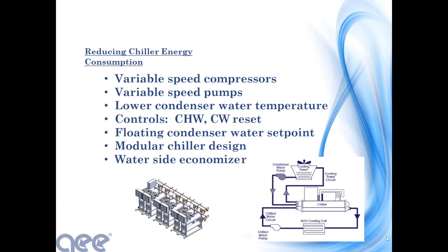So we recognize that with most of these electrical mechanical chillers, you're optimized at 50% load. So if you have, say, 2 chillers in a building, and your strategy right now is to run one as the lead chiller, and when it gets up to 100% load and you still have more cooling load, you kick on the second chiller. That's a lot of strategies right now.